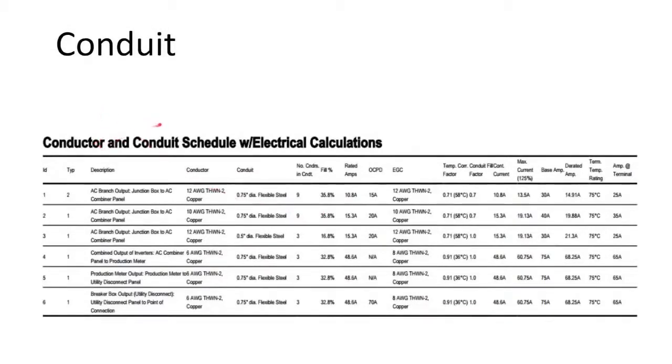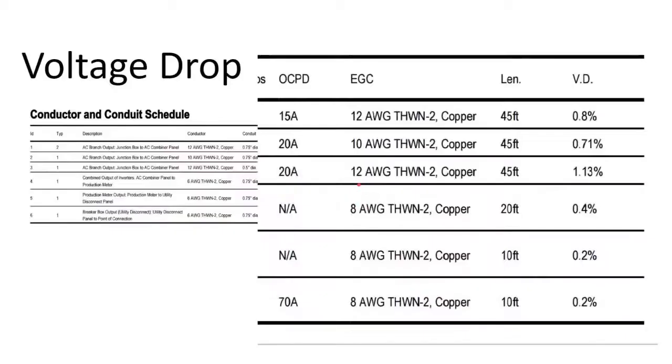So here's an example of a conduit schedule where, I know the print is fine, but it's telling you you have a combination of 3/4 inch and 1/2 inch and 3/4 inch conduit. You might go back into this software and say, okay, it's all going to be in 3/4 inch. So we're going to upsize our conduit, and that'll change your conduit fill calculations, and gives you a good glance at your balance of system material as well.